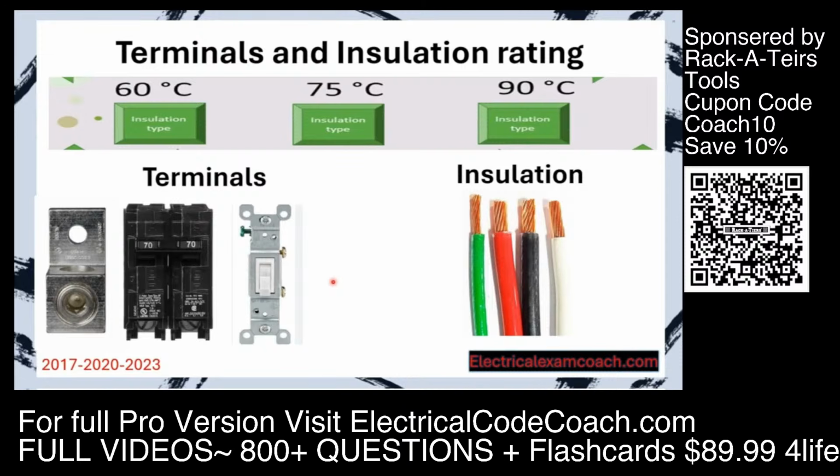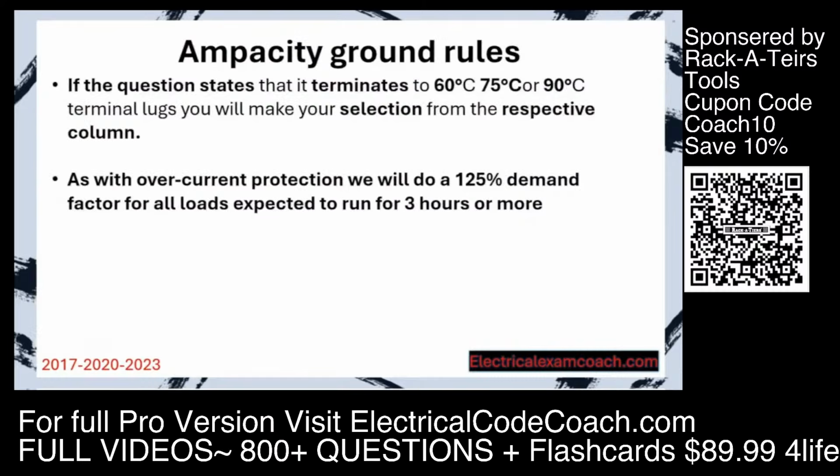just like other sections of the NEC. There are blanket rules that apply generally, but later they get modified. But for right now, what I want you to remember is we're going to match the column that we used based off the terminals that the device is rated by. Regardless of what the insulation is, we can choose from whatever column that the terminals are rated by, unless modified by another code. Now let's lay some ampacity ground rules.